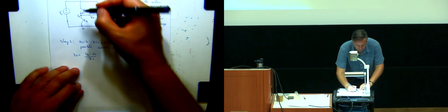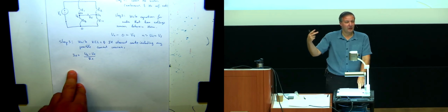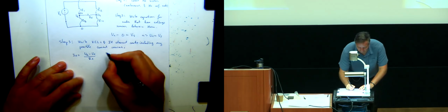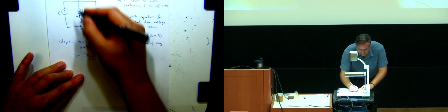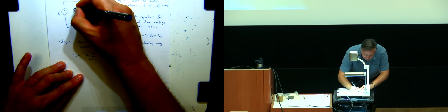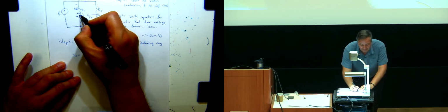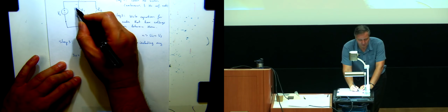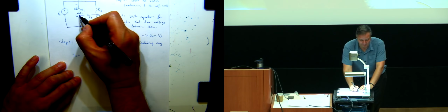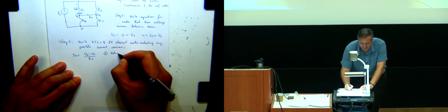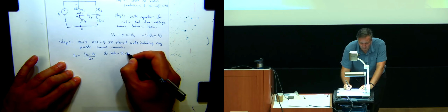What I've done here is two equations in my head. The first equation, which I skipped, was that there is this voltage V element 1, because I labeled the current arbitrarily. Now I have to use a passive sign convention for V element 1, so I have to orient the plus this way. Then I can say V element 1 is equal to I1 R1.